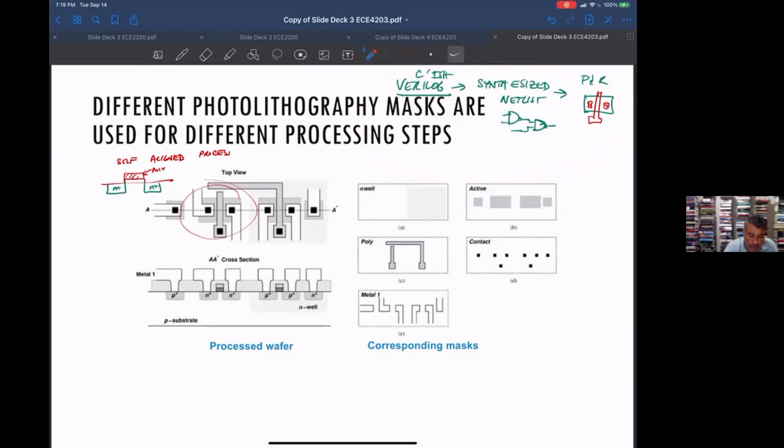But the good thing is the majority of your chip is not running that fast. If you have a 2 gigahertz clock chip, most of the chip is just not running that fast. There are just a few data paths running at that speed. And that's when you have to hand hone some of the stuff. Okay.